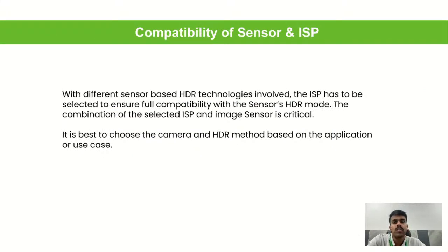One of the most commonly talked about problems is that, like I explained, each different HDR methodology is supported by different sensors, and they are not compatible with all the different ISPs. In almost all scenarios, the sensor has to be paired up with a specific ISP that can support it to take advantage of the HDR method. So we need to make sure that we choose the sensor as well as the ISP that works specifically for the HDR method that is chosen.